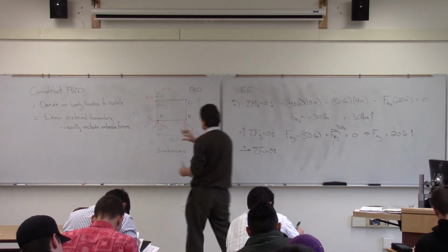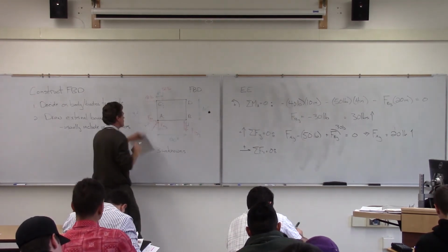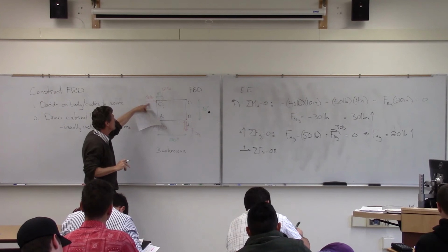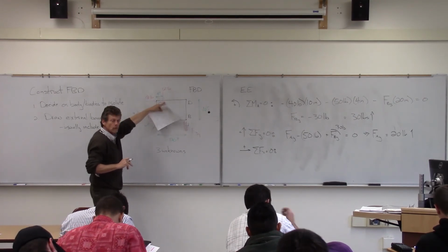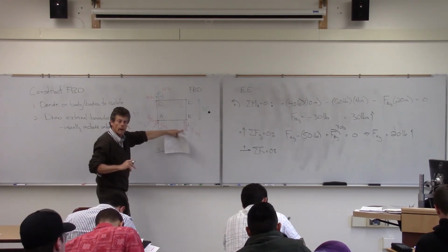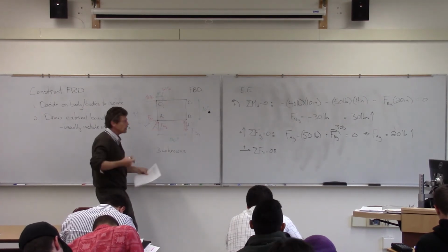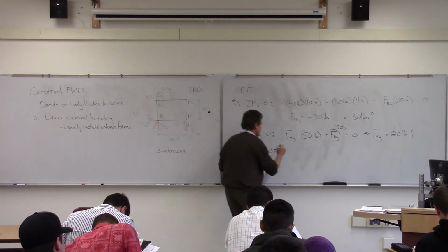And then our next equation will be the x components there. So I'll just look at the various pieces there. I got the FAx. I got the 40. The 50 will not participate. The FBy will not participate because they're acting vertical. So that's an even easier equation.